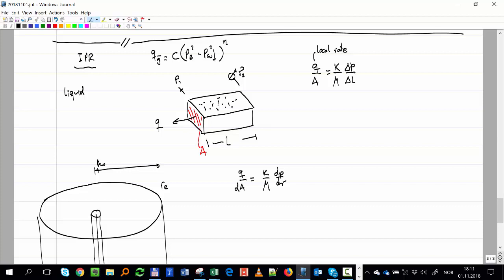If you see that up close, this area is not completely open, but it has a lot of pores through which the fluid circulates. So if you want to take into account the real velocity, let's say the sum of all of these areas will be the area of the pores.